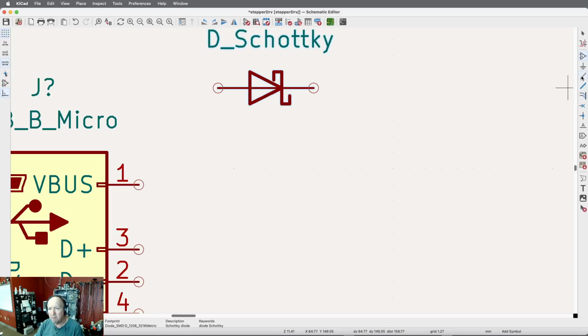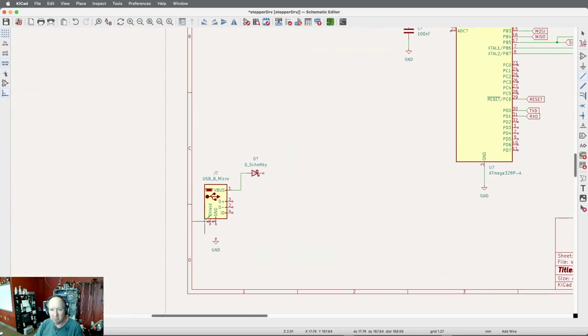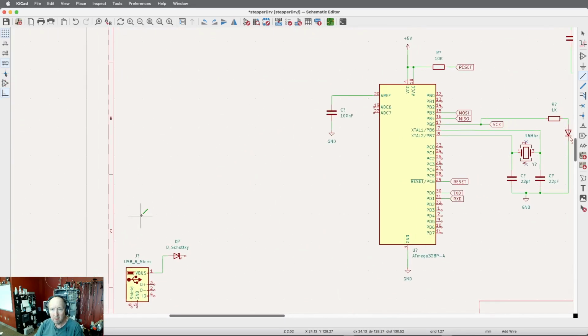Okay, so then let me wire this in. So this side is actually the side that goes to plus 5 volts. So what I need to do is come back up here. I keep hitting the escape key. That seems to help a lot when I get things not working the way I want. So I want my 5 volts. I need that to go here. And then I need to get that other part, that CH340, USB to serial adapter.